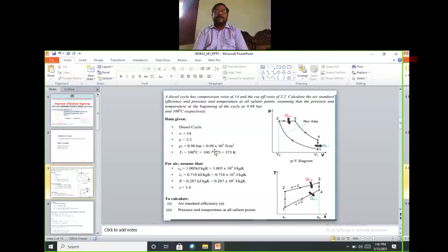For any problem in applied thermodynamics, you have to study the problem twice, very carefully. You have to write the given data. First, go on studying the problem with the correct notations. Diesel cycle means you must write the PV and TS diagram. That is the first step.